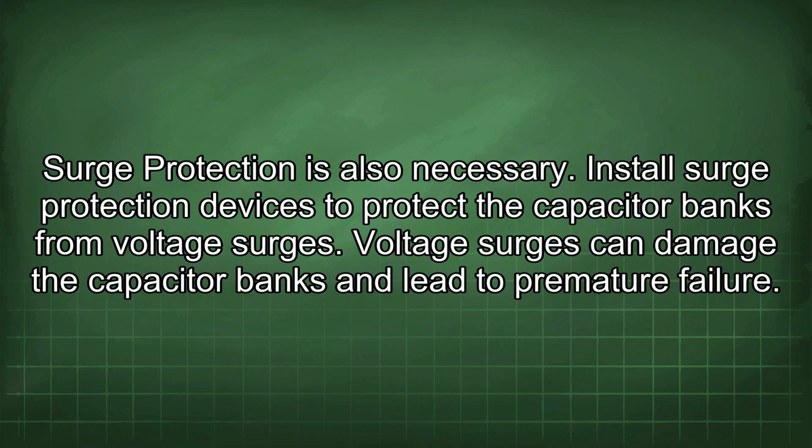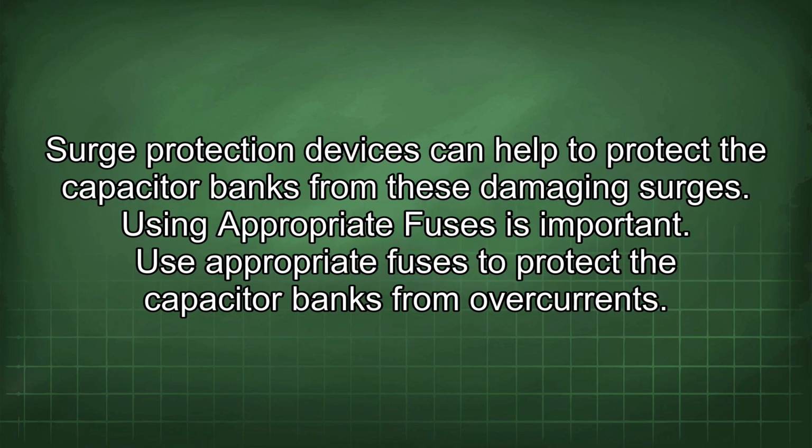Surge protection is also necessary. Install surge protection devices to protect the capacitor banks from voltage surges. Voltage surges can damage the capacitor banks and lead to premature failure. Surge protection devices can help to protect the capacitor banks from these damaging surges.